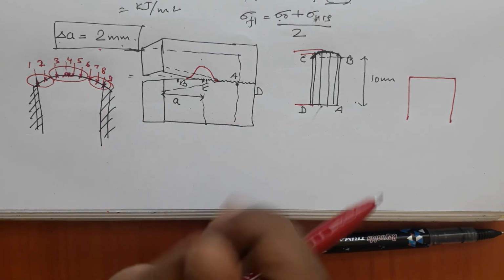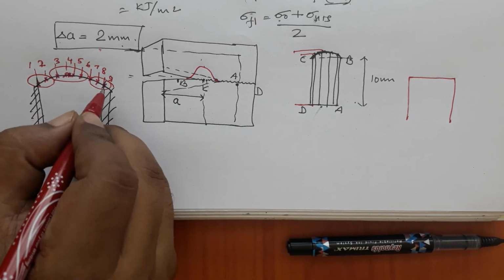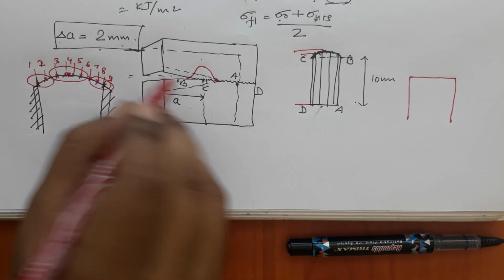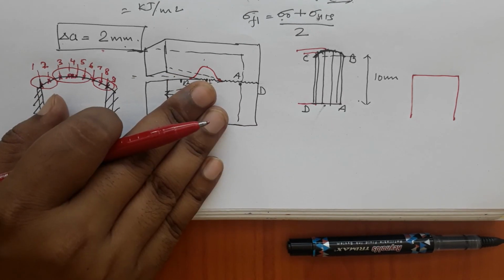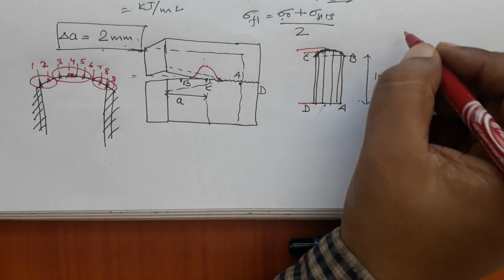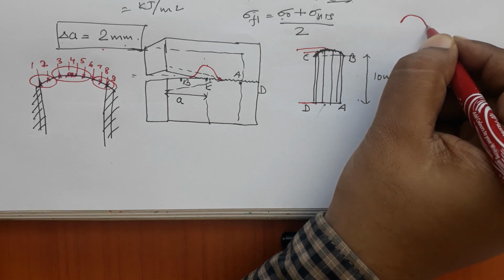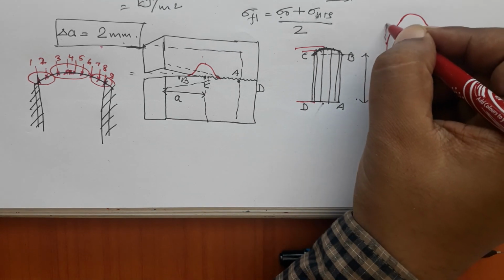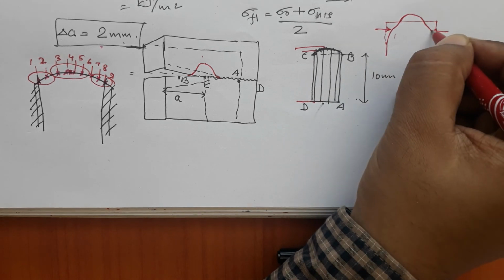If you have less constraint, that means material can flow a lot because it is relatively free. So, the crack will not grow that much there, right. And that is why if you look at it from this side, okay, if you look at this specimen, if you do this kind of testing and look from this side, or from top also. So, initially if the specimen was like this, after deformation the crack will grow like this, and then it will actually be like this. And initially it was like this, okay.